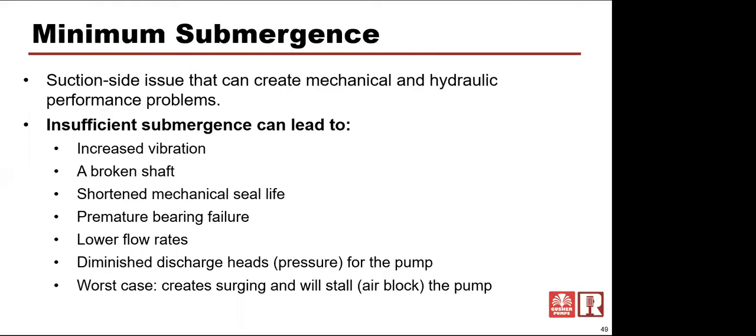And when that velocity is at a certain flow rate, or certain velocity flow rate, you can draw air through a vortex or column of water, looks like a tornado, down through the water when the water level gets close enough to that drain. That's what happens. That is a vortex. That is air entrainment. So the drain that's going out of there contains water, but it also contains air. It's easier to suck air into it than it is to suck the water into it when that water level gets low enough.